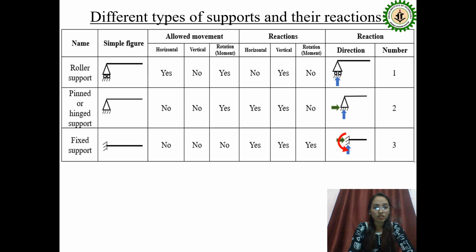And for fixed support, there is no movement at all. That means the reaction will be in all 3 directions. That is horizontal, vertical as well as rotational. So there will be 3 reactions. Okay.